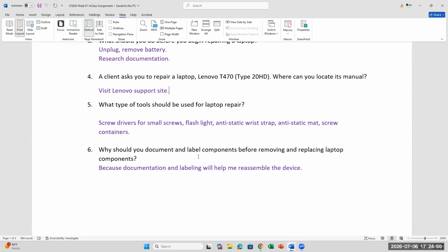Now, some anti-static mats have a wrist strap, so I'll give you some of those. What you do is you clip it to the metal case or metal area of your workspace. What that does is it keeps your body grounded. And so, number one, you don't get shocked. Number two, you don't shock the system, right? Because static electricity is going to cause damage to RAM, the motherboard, and other things. So what you want is some of these components.